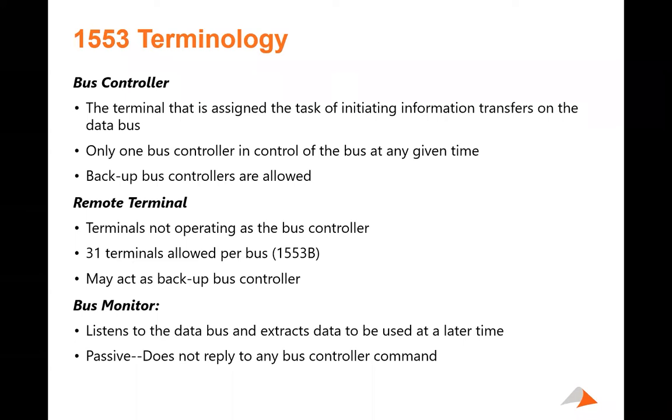Let's see here. Bus monitors. Bus monitors listen. They never transmit. If it transmits, it's no longer a bus monitor. Abaco has two different kinds of bus monitors too. They'll have one that follows the strict sense here that connects directly into the data bus on a coupler, and then they have one that's a high impedance. And high impedance monitors can be really nice because they don't affect the impedance on the bus.